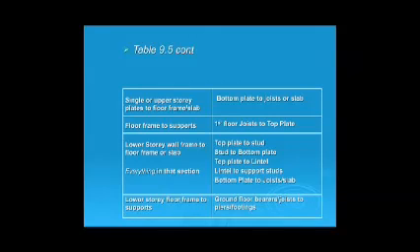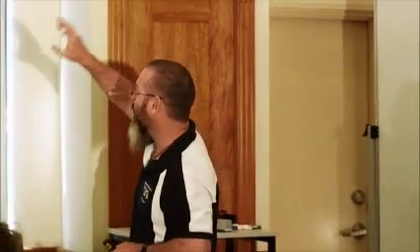As I said before, it matters whether you've got a sheet roof or a tiled roof because it contributes to uplift. But if you think about it, the uplift up there at the top of the building, because there's not a lot of weight at the top, will obviously be significantly higher than it is at the bottom plate, because you've got the weight of the building on top of it. So as you go down through the building, the pressure actually reduces, and you can see that in the table.